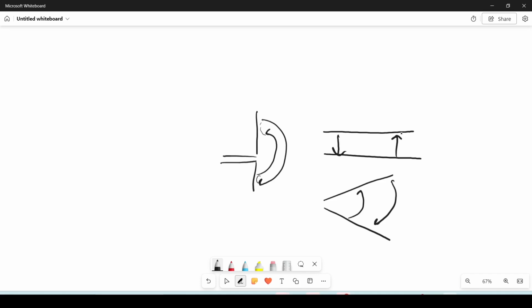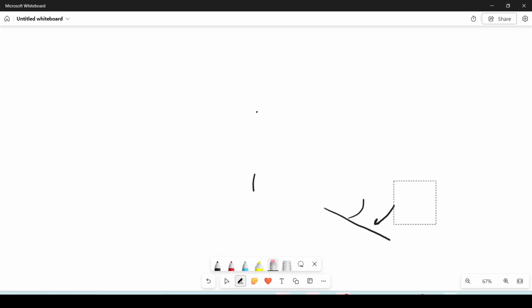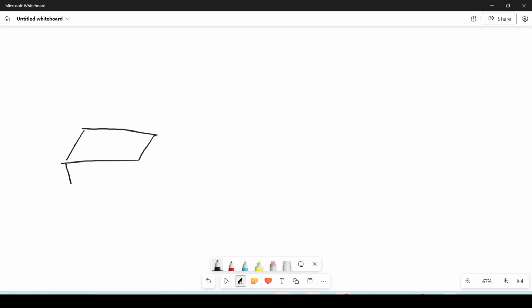So we have a transmission line, the guided medium, and then we open it, and then the field fringes in this way, and then it goes to the far field. Similar to this is the patch antenna, but the mechanism is a little bit different. In the patch antenna, it generally starts like we have a metallic cavity. This cavity is like this and has some modes inside, some field distribution depending on the dimensions, which decides the cutoff frequencies and so on.